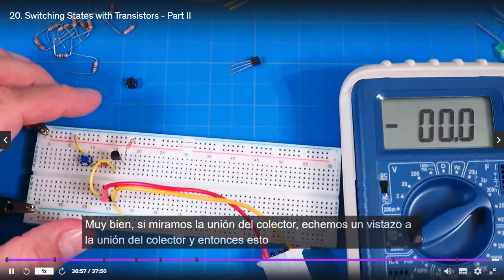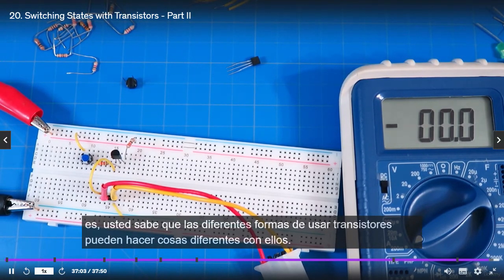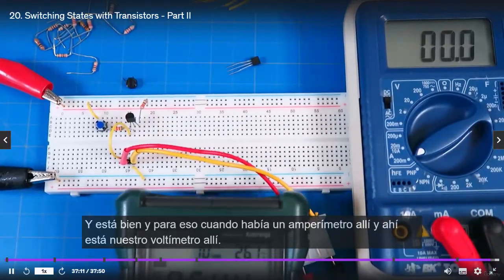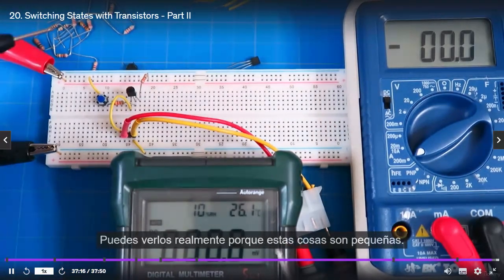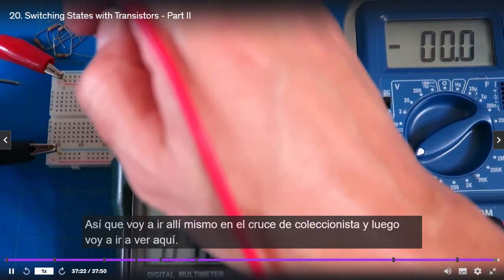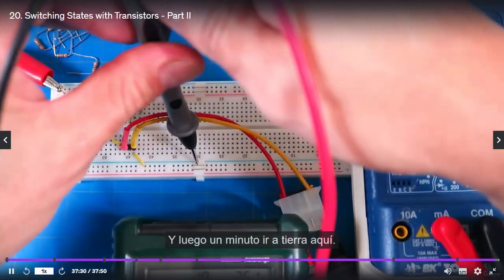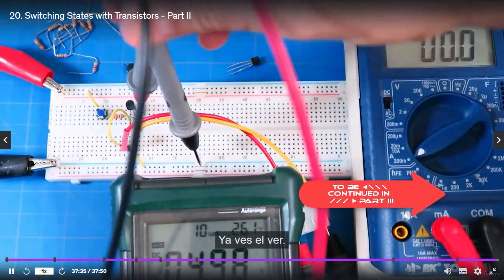So let's look at the collector junction. These are different ways of using transistors; we can do different things with them. Let's get our meter here. I'll put that one there so you can see our ammeter, and there's our voltmeter there. I'm trying to keep things close so you can really see them because this stuff is small. I'm going to go right there to the collector junction, and then go to ground here.